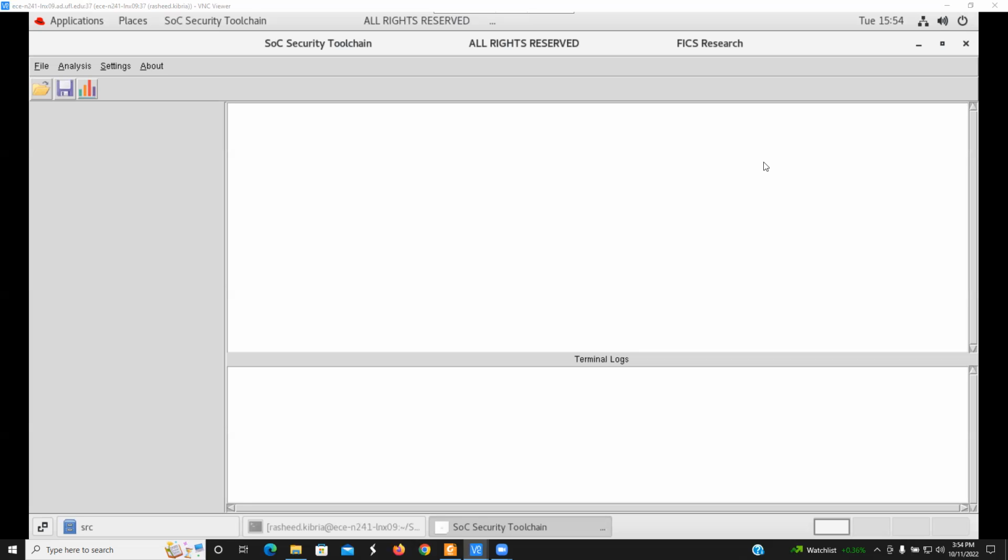Of course, that is basically absent in the RTL abstraction because many of the state transitions can be detected after synthesis at the netlist level, which is not possible to find in RTL abstraction because RTL is such an early design stage. So we may not have many real state transitions before implementing or synthesizing that into hardware.